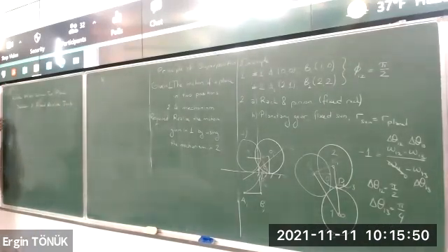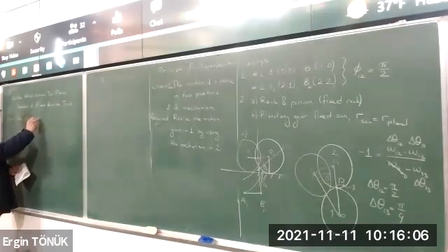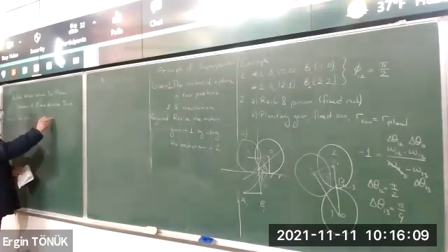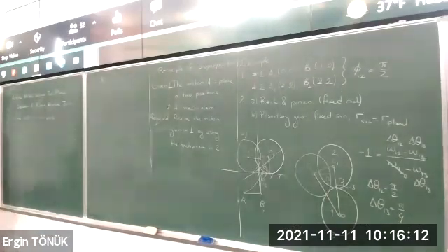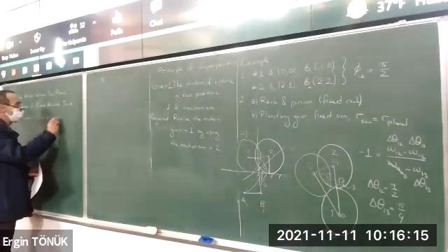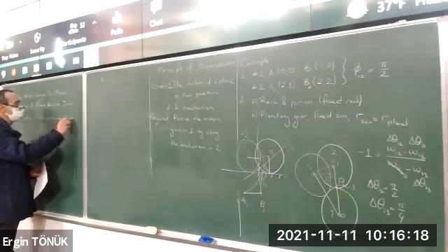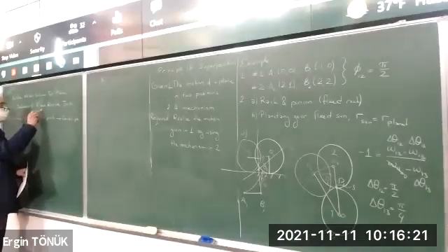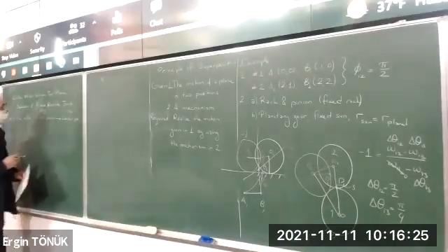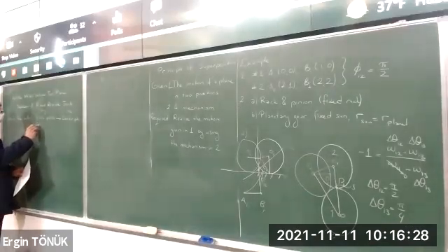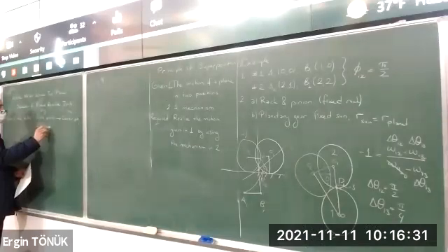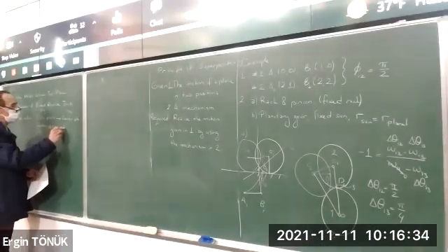Now, the solution, as you suggested, is invert the motion. Then what's going to happen? The circle points, that is the moving pivots A and B, will become center points in the inverted motion. So this is original motion, this is inverted, and center points will become circle points.